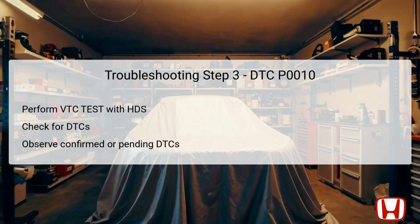Following the engine warm-up, the next step is to conduct the VTC test within the HDS inspection menu. This test specifically evaluates the functionality of the VTC system, which is crucial for determining whether the oil control solenoid is operating as intended. After the test, check for any confirmed or pending diagnostic trouble codes once more. If DTC P0010 is still indicated, it confirms the legitimate presence of a malfunction.